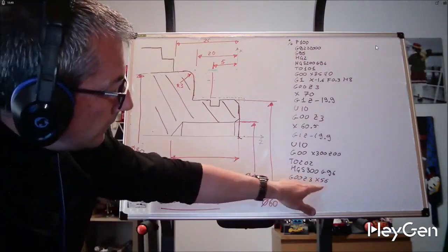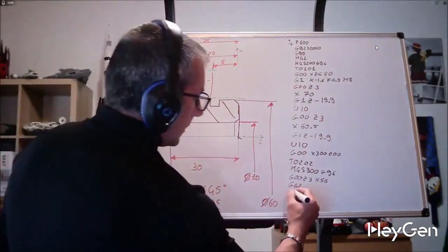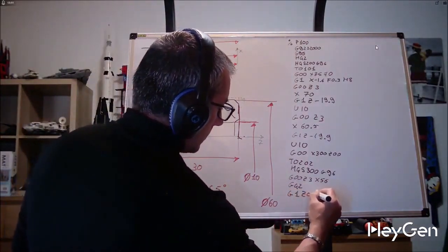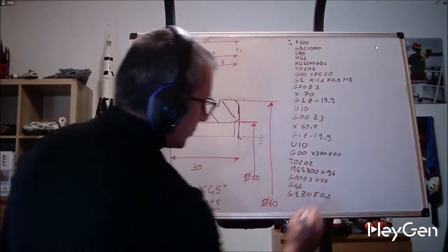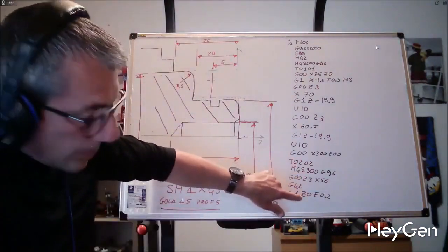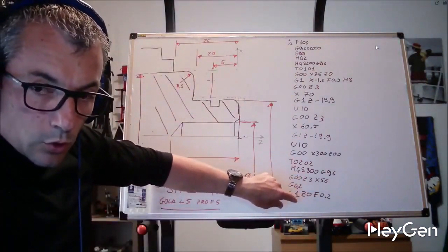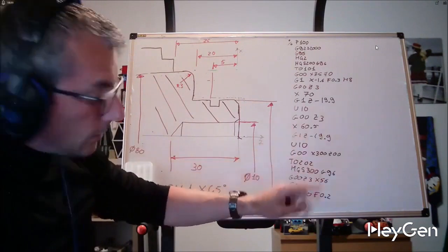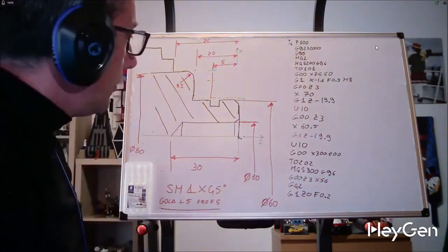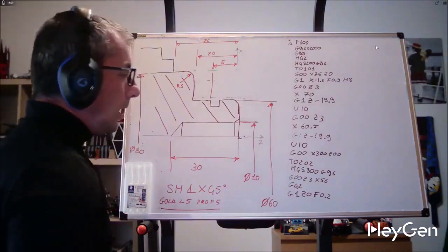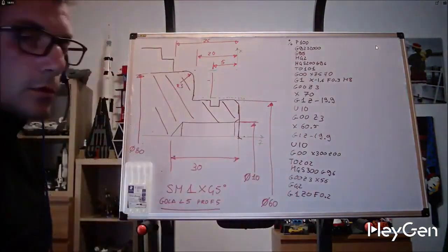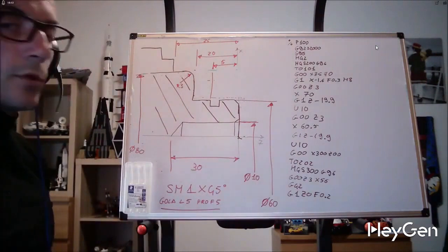Now notice that I have arrived at G00 and only after set G42, Z3, X56, then G1, Z0, F0.2. The first movement, Z3 to Z0, must always be at least twice the radius of the tool. Otherwise, on some machines, G42 can be a bit troublesome. At this point, let's do our chamfer. Let's make a cool chamfer.